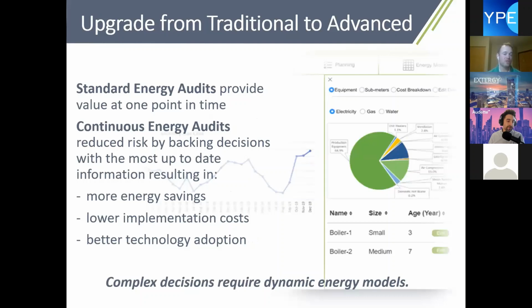As Chris mentioned, we take a similar approach. We want to make sure that these models are dynamic. So as they change, whether we're connected to monthly energy billing or we're connected right up to submeters, we want to make sure anytime a new data point comes in, the energy model has the ability to update. As an energy auditor, when you build a model, you're literally looking back at energy bills for the last 3 years. So you get 36 data points and try to build something that would fit what you've seen as actual data or evidence in the real world.